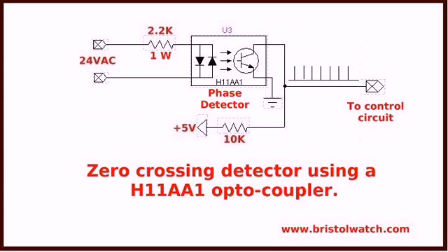Hopefully now you've got an idea how to program interrupts, and we know how to get them to react with a switch. Now we're going to look at a direct application that I've had up on YouTube before. This is a zero crossing detector. What it does, it produces a pulse from low to high at 0, 180, and 360 in a sine wave. These pulses are a way to synchronize to the AC power line, so you could use a microcontroller to control various power circuits.